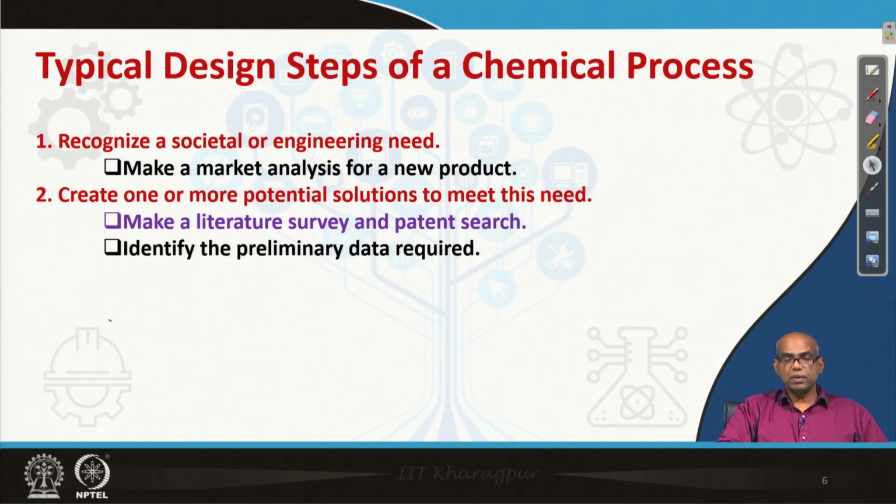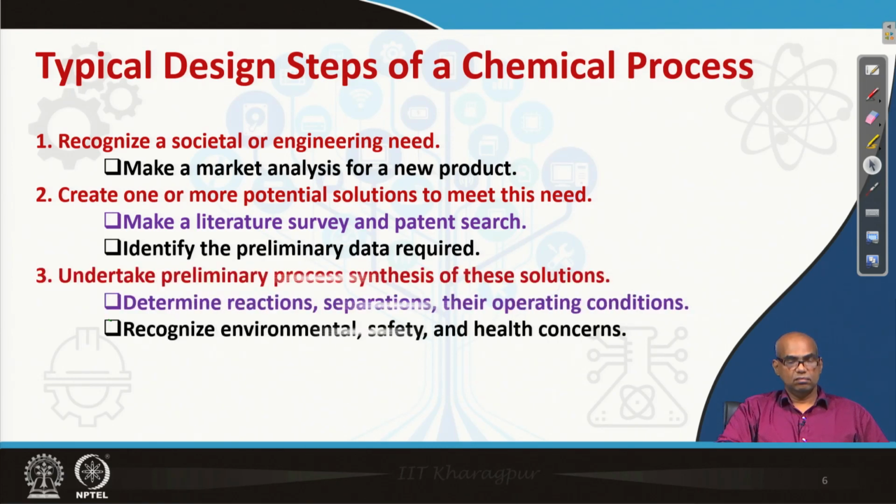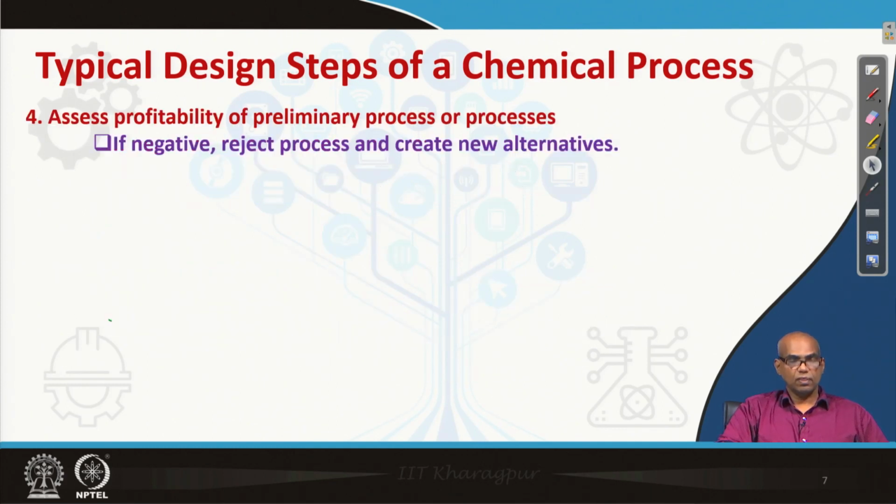Make a literature survey and patent search, identify the preliminary data required, undertake preliminary process synthesis of these solutions, determine reactions, separations, their operating conditions, recognize environmental, safety and health concerns, assess profitability of preliminary process or processes.